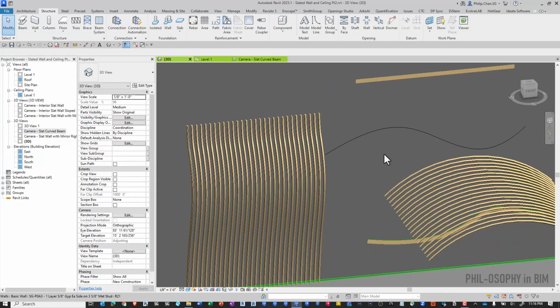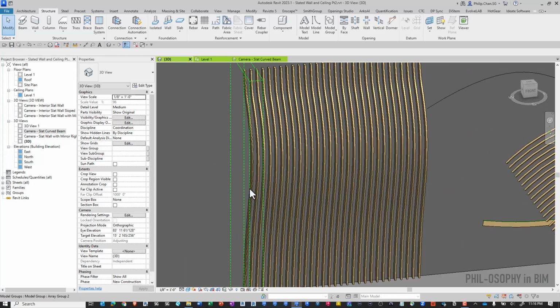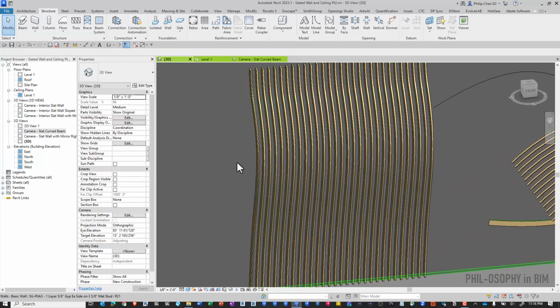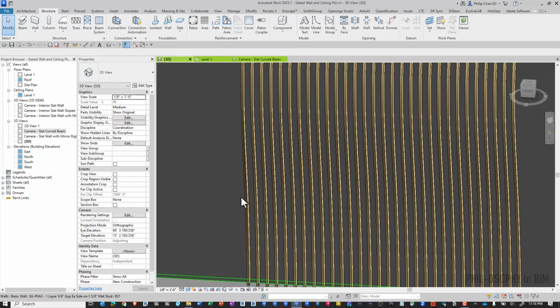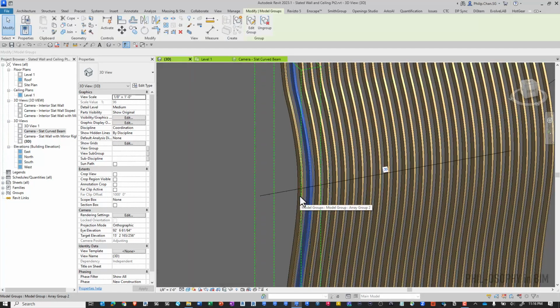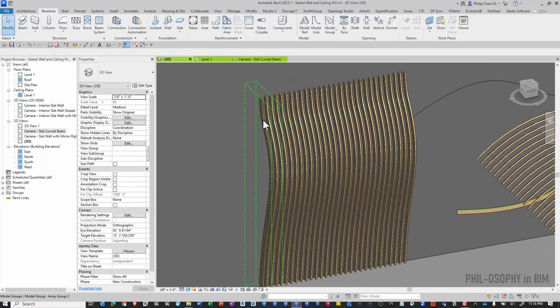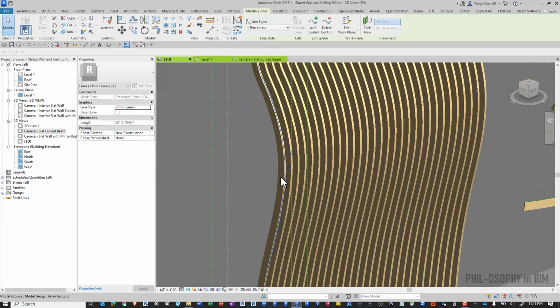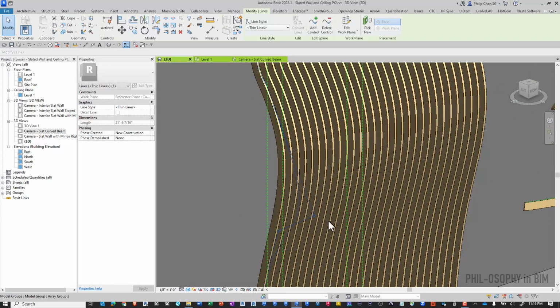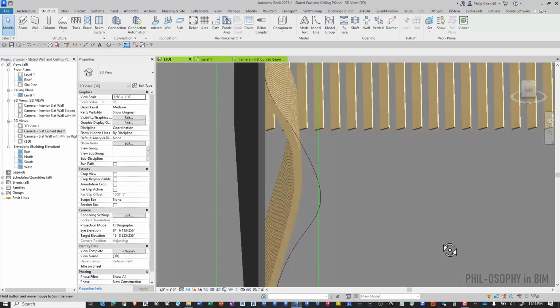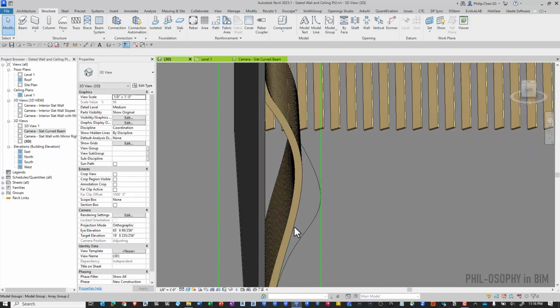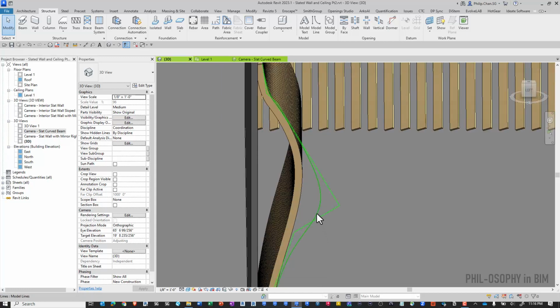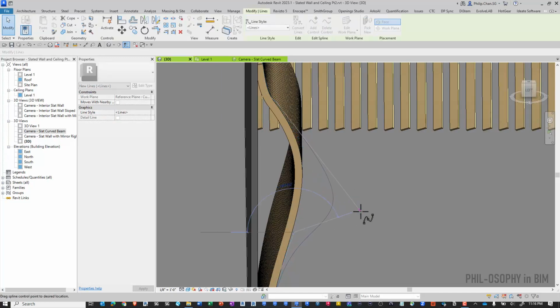One thing to remember in this case is, because I have my model line drawn here, after I use pick line, if I ever update my model line, let's say I pick this one over here, and I adjust the shape of the model line like so, you can see that my beam is not going to self-adjust to the shape of my model line anymore.